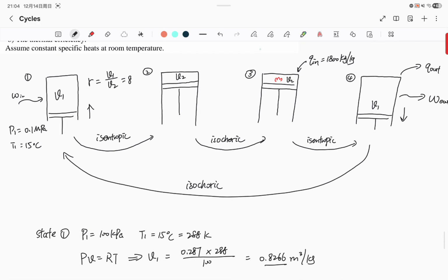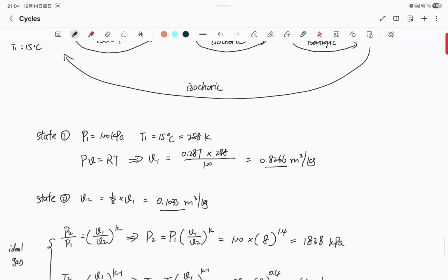Why closed system? Because we got a piston inside the device. We're gonna treat it as closed system, but in real life it is not, because we got exhaust, the valve's gonna open, there's mass entering the boundary, but here we're gonna just treat it as a closed system.